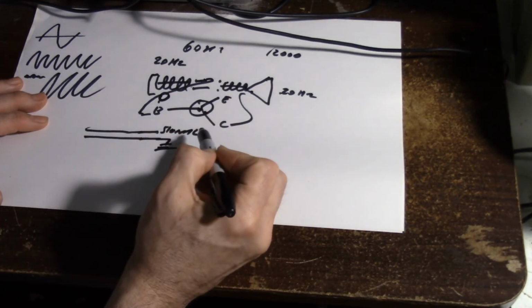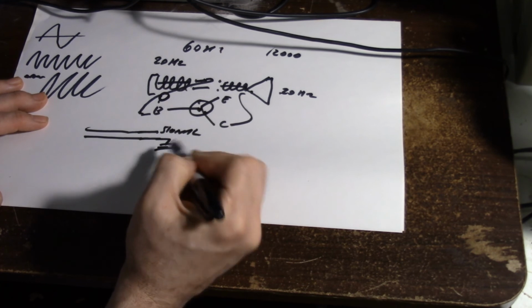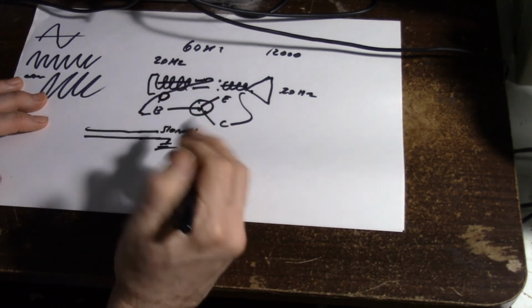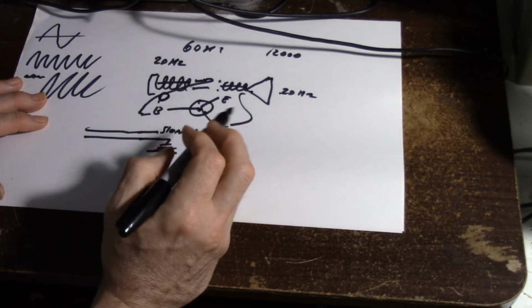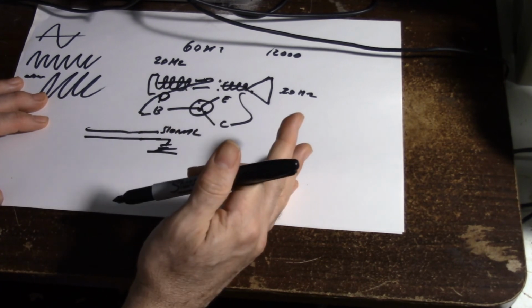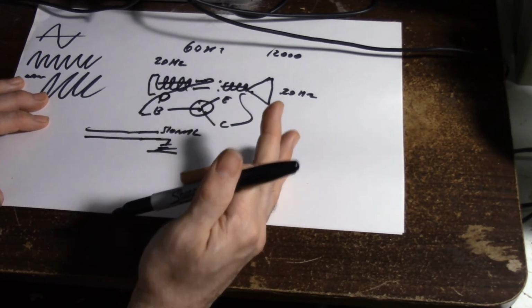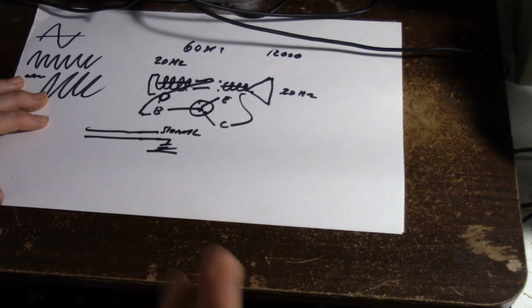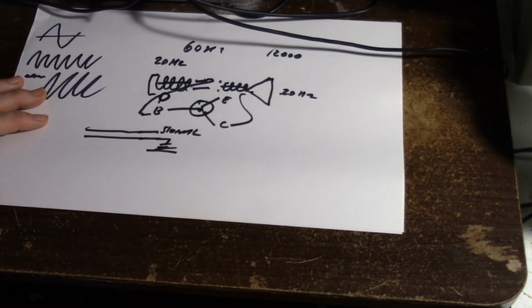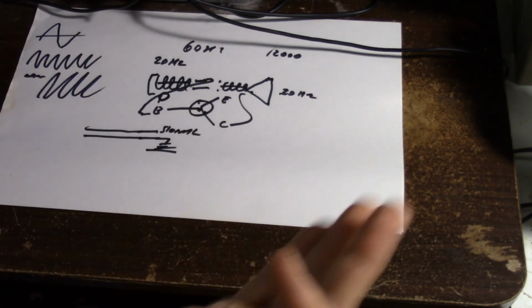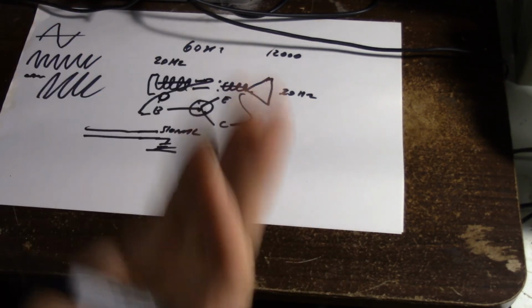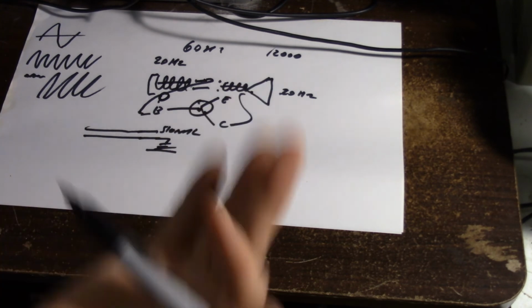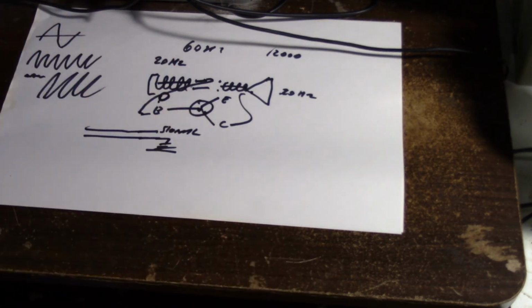So the signal goes, comes back, goes to the ground. The problem with this is that because the ground is actually part of the signal wire, it picks up a lot of interference. So with long stretches of cable, you'll pick up everything. You can pick up interference from fans, anything electrical. You might even be able to pick up a radio station.